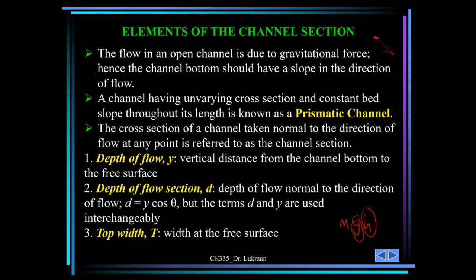Like I said, you can also have gravity to facilitate flow in pipes. When you have a tank at higher elevation and you connect the pipes, this is the pressure head in the tank, and then the fluid can easily flow in the pipes. And this is also gravity, because you raise the tank above to increase the potential energy of the liquid in the tank.